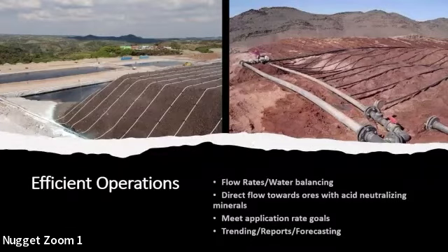What were the particle size limits and heap stack height limits for the flex wall testing? Typically in this particular one, 2 inches is the particle size limit. For the 12-inch column, that was the maximum. And the limits in terms of what we could test down to would be equivalent to 80 feet of depth within the leach pad.